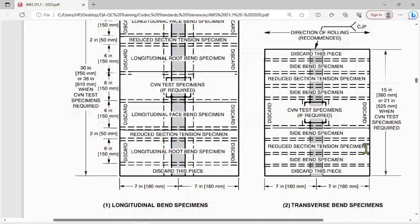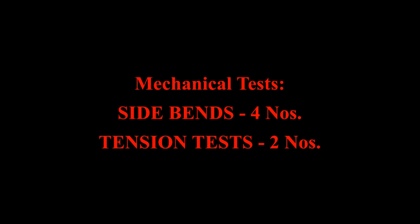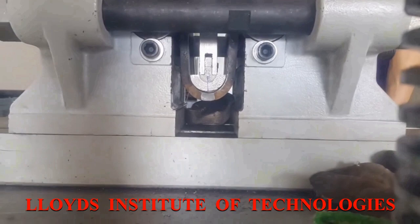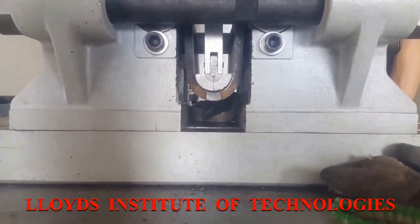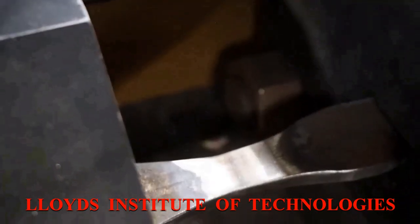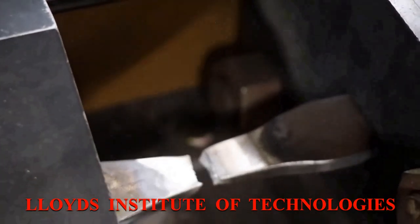This is for the tensile test, to get the tensile strength, yield strength and elongation, etc. So you need, I repeat, four side bend specimens and two reduced section tension specimens.